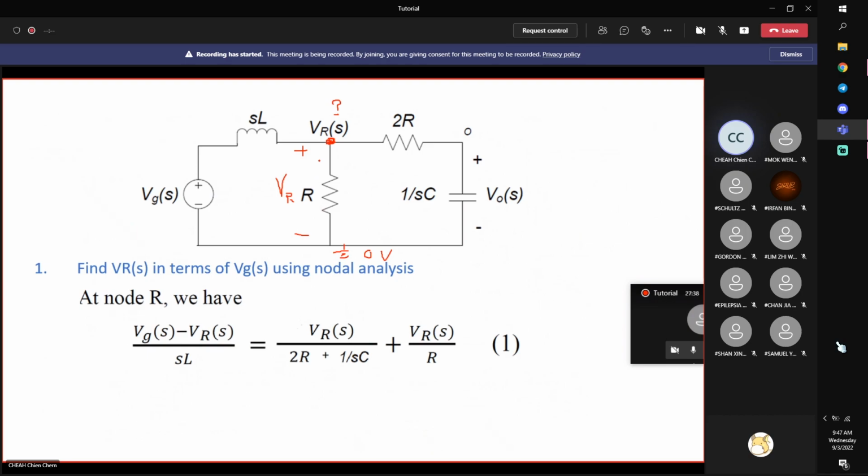So we are trying to find the voltage across these resistors by using nodal analysis. And nodal analysis says that if this is not known, call it a variable VRL, then write down an equation in terms of VRL and then solve the equation. How do we write down the equations? By KCL. So if you use KCL at node RL, you have inflow equal to outflow, for example. Now, this is assumed.